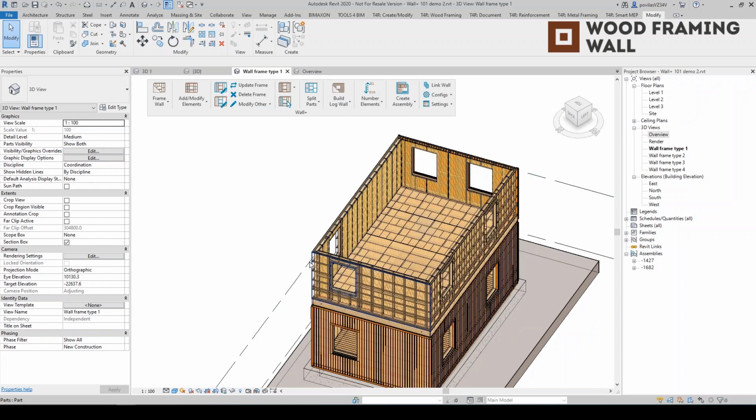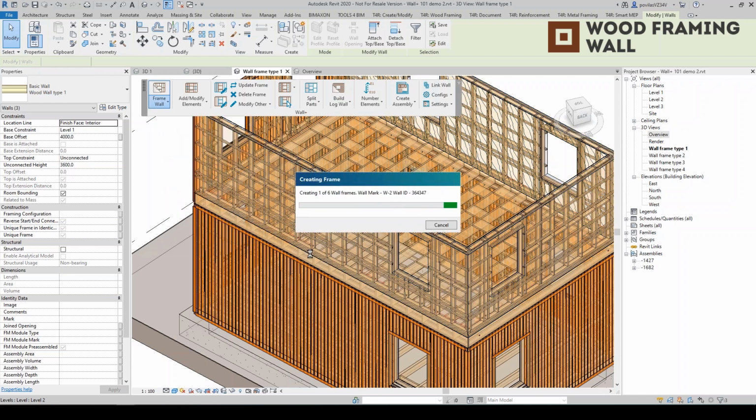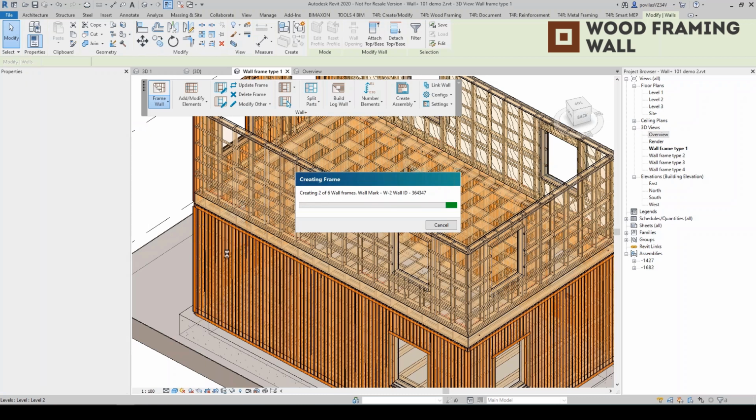So just quickly switch back to original, and we're going to add siding to this wall. Three walls selected, drop down menu, add siding. Okay, there are two layers of siding per wall. As you see in this example below, vertical siding, one layer is those timber slats, and then the next layer is just the trimming around the edges. Again, that can all be customized. This can be wider, thinner. I mean, it's limitless, so you can build your own bespoke configurations for siding as for anything else.